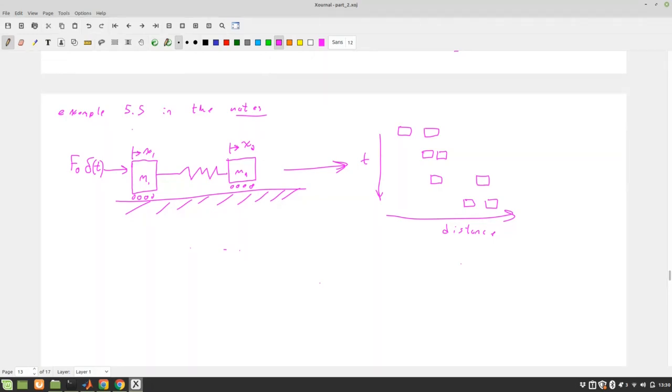Force is mass times acceleration, and there's a force, and there's nothing counteracting it, so it kind of has to move in that direction. All right, but for the first initial setup, we need to build our equation of motion. If I tap x1, what's going to move more, x1 or x2? X1, right? So we're going to assume x1 is greater than x2. That work? You can assume the other way. You'll get different equations, but you should get the same answer.